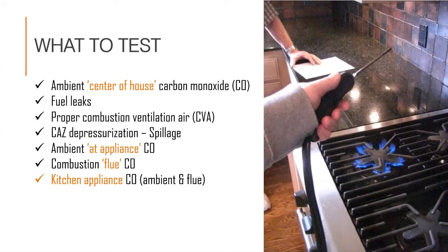We'll check the flue levels of carbon monoxide at each appliance, noting that the kitchen appliances each have their own ambient and flue level as well.